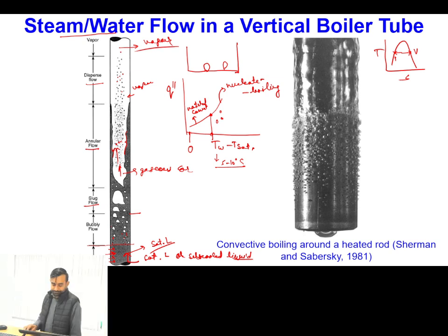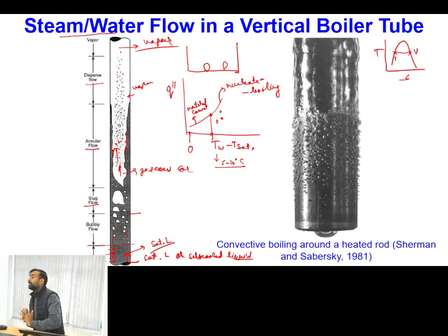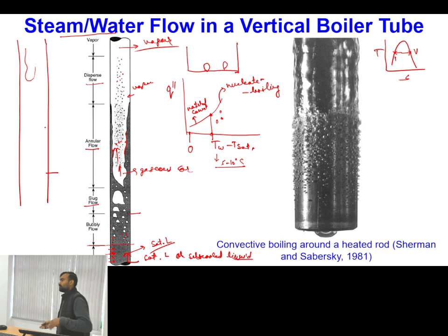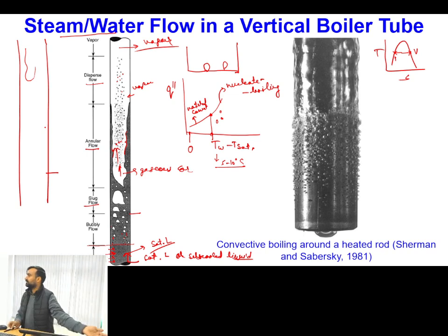So you can see that if you simply control the flow rates of the two fluids in an adiabatic situation, your flow regime remains the same, and after leaving the entrance portion, it remains the same in almost the entire pipe. So if you have an adiabatic flow pipeline and its length is significantly high, so that entrance effects are negligible, whatever phase distribution you get can be extended to the entire pipeline and the analysis can be done.